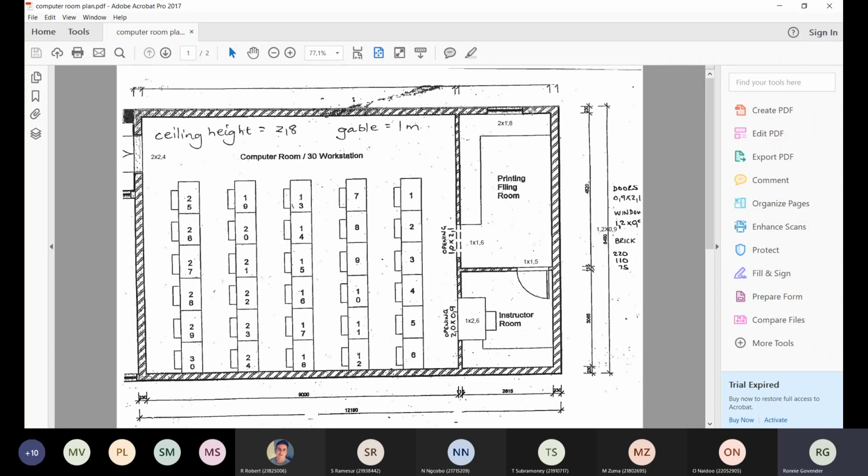In other words, you need at least one brick length so that it gives you support. You place your lintel as though it's occupying one brick there. Now, a brick is normally about 230. We just add 300 to be on the safe side. Just add 300 to each lintel. So that's how I get 2 by. Normally, I would have needed a 1.2 meter lintel, but because of 300 on that side and 300 on that side, that's why I got 2 by 1.8. You all understand that, class? I'm going to need two lintels 1.8 meters long because I need a 300 overlap on either side.